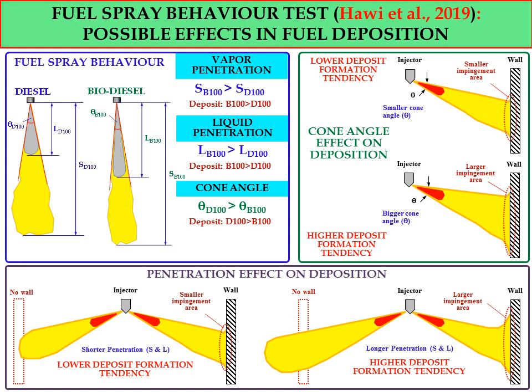However, we cannot rely on this one alone, because B100 has many factors that will cause a greater amount of deposit formation compared to diesel fuel, such as the high density of B100 fuel, and also the different behavior and higher drop lifetime compared to typical diesel fuel.